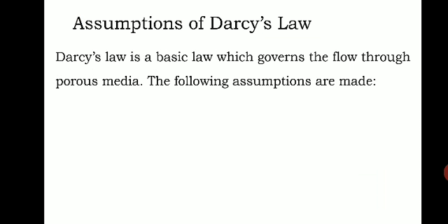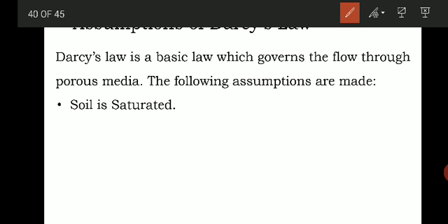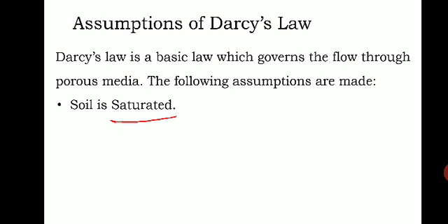Then we'll see what are the assumptions made for Darcy's law. Darcy's law is a basic law which governs the flow through the porous media. So the following assumptions are made. The first is the soil is saturated. Saturated here means it is completely filled with water. So the soil should be saturated, that is, it is an aquifer, which holds water.